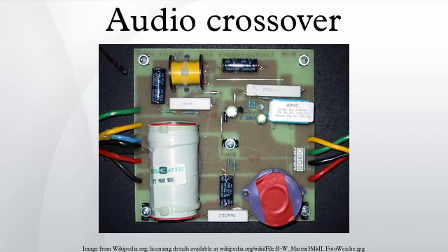Digital. Active crossovers can be implemented digitally using a DSP chip or other microprocessor. They either use digital approximations to traditional analog circuits, known as IIR filters, or they use finite impulse response filters. IIR filters have many similarities with analog filters and are relatively undemanding of CPU resources. FIR filters, on the other hand, usually have a higher order and therefore require more resources for similar characteristics.